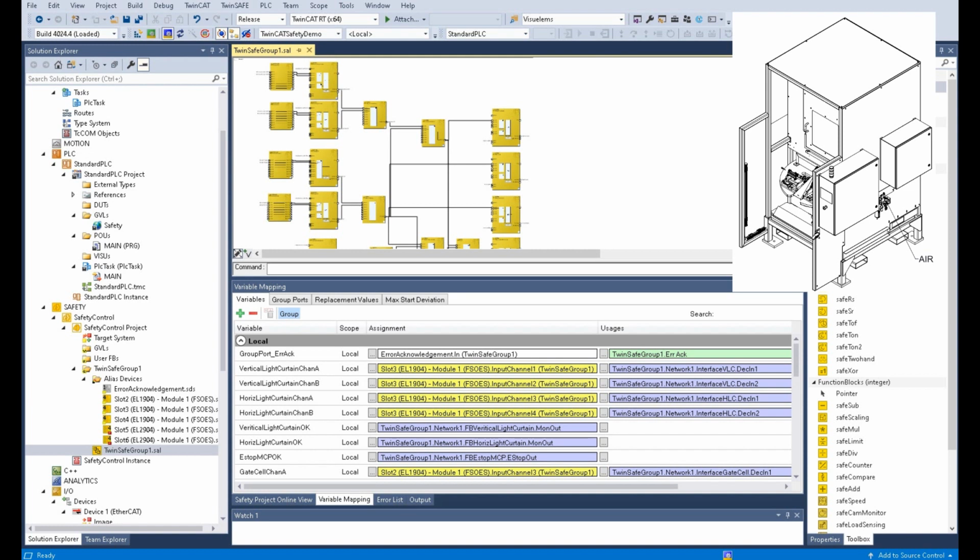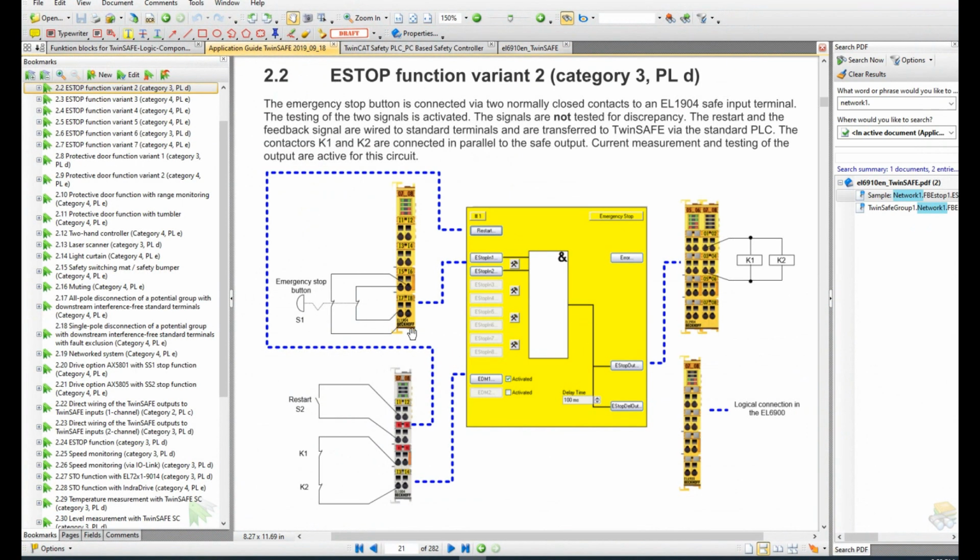According to our application diagram, for example for the e-stop loop, we already programmed the safety input, safety output, as well as the core logic. However, we haven't connected this area, for example the EDM signal. As shown on the screen, this K1 and K2 come from the relays K1 and K2. And this K1, K2 EDM signal is a normally closed signal coming from the relays. Both signals come from the standard card. And for the reset, usually this reset signal also comes from the standard PLC.